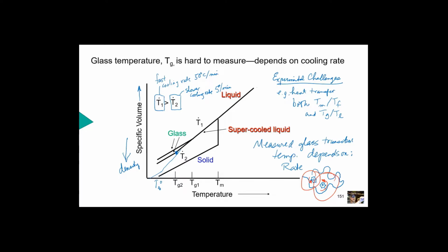There's a kind of a crankshaft. If I get closer to the camera here, maybe like this. There's this kind of motion as we look at the bonds. It's a kind of crankshaft motion. And that'll be different at the ends of the chain than it might be in the middle of the chain. So there's all sorts of things that go on to keep this glass transition measurement kind of a complex thing. What if the polymer chain was at the surface and it's constrained to stay near the surface? Well, there's a whole large group up at Case Western Reserve University that got millions of dollars studying just that effect. We talk about a glass transition, and one of the reasons we're interested in it is because glassy polymers are brittle and hard.